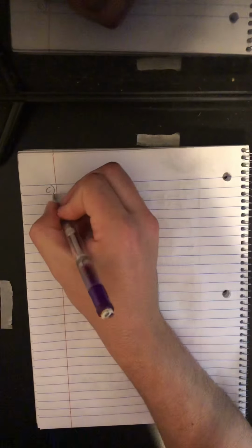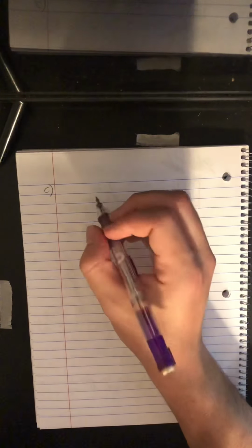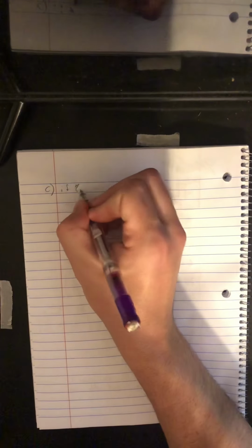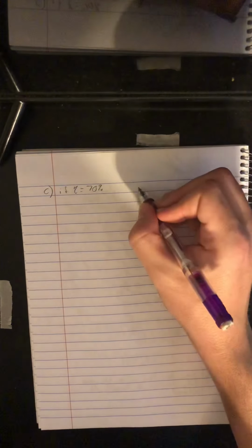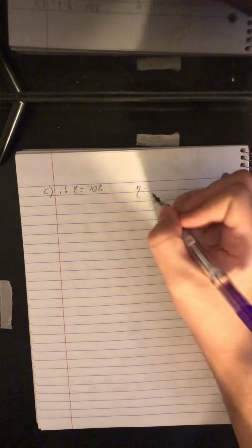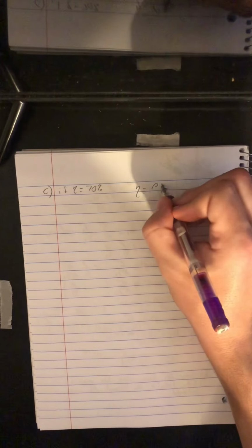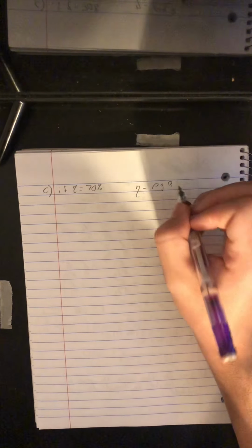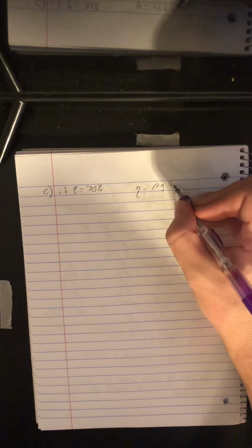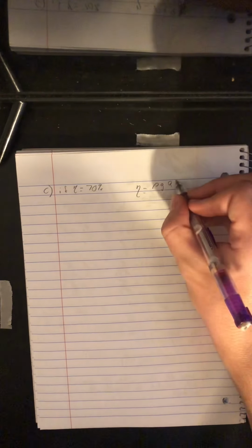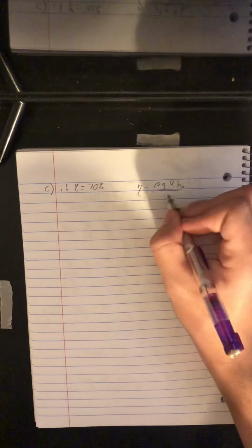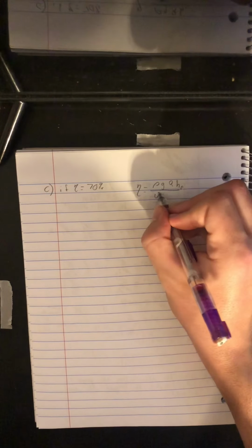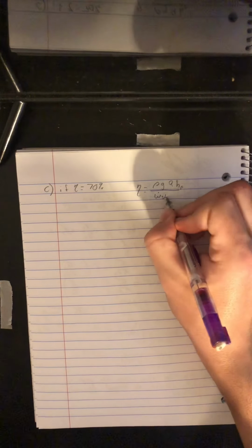All right, so now quickly do part C. And this is if the efficiency is equal to 70%. So the equation for efficiency is equal to density times gravity times flow rate times the head gain over, this is the ideal work or power given, and this is W dot shaft.